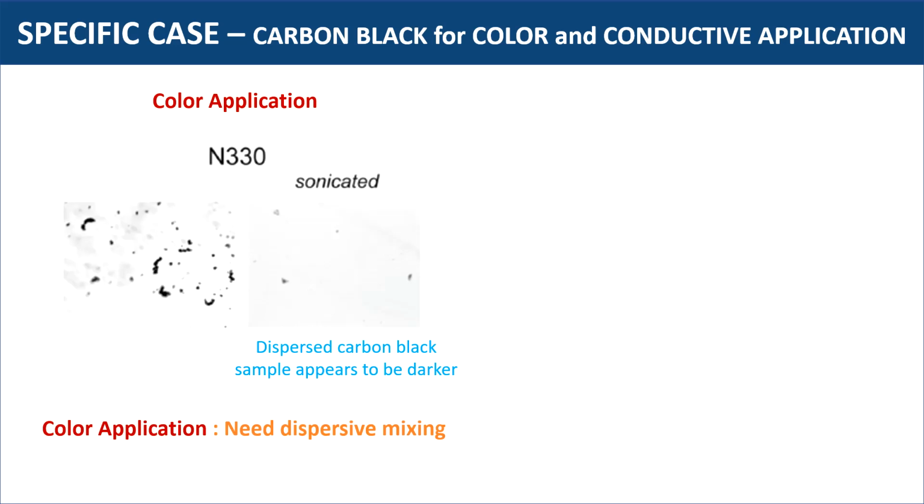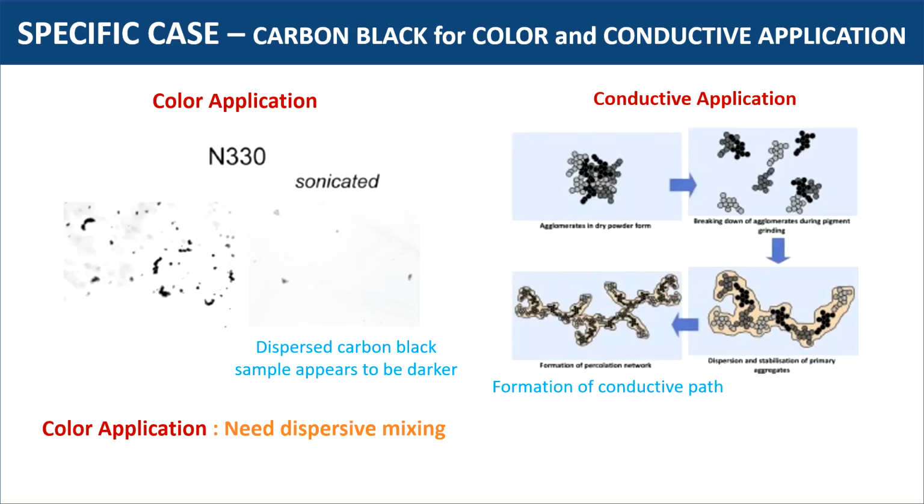But if it is used for conductive application, which requires formation of a conducting path, we would not like to have excellent dispersion, because if it is in an excellent dispersion state, then individual particles will be equally distanced from each other and there will be no conductive path formation. Therefore, in the case of conductive application, we need moderate dispersion but excellent distribution of carbon black.